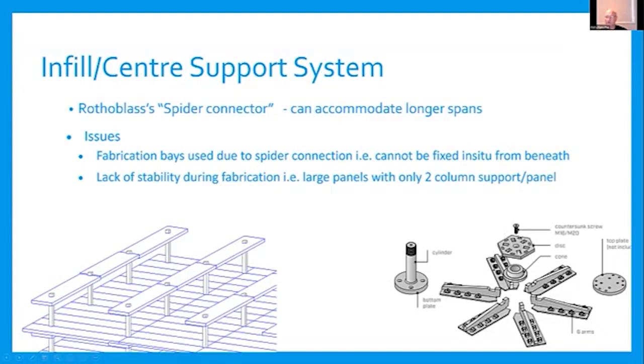It would probably be better for these to have studs, like I'm thinking like an engine block type stud, where they come down through the plate, and this particular ring can be more easily fixed to it on site. We found that from our point of view in Australia, we'd prefer to do fixings from underneath over on the deck here, if you follow my cursor, fixing up underneath, than having someone on a live deck. And so this tended to dictate the process that we adopted for this particular approach.